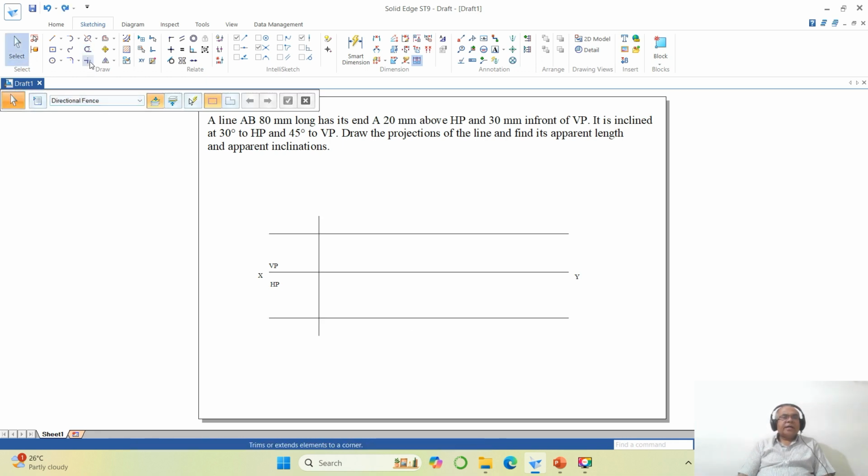You have a trim corner. You just click on this, select inside line here and here. So automatically those two will both be trimmed. Similarly, you select this line and this line. Now you have two horizontal lines.